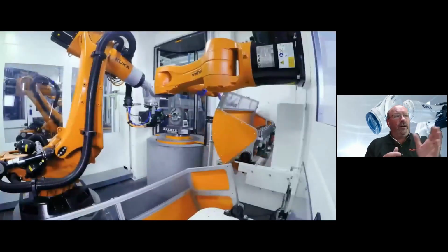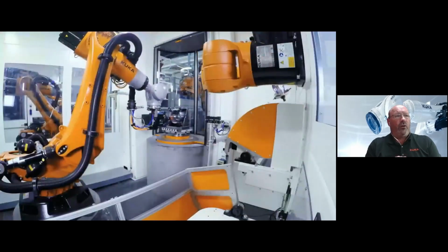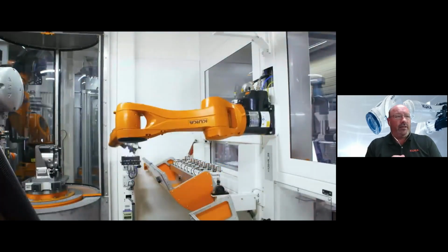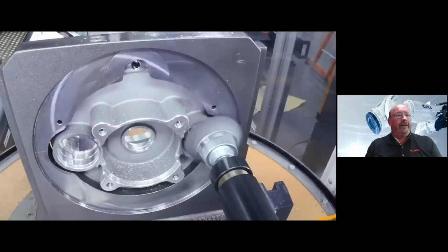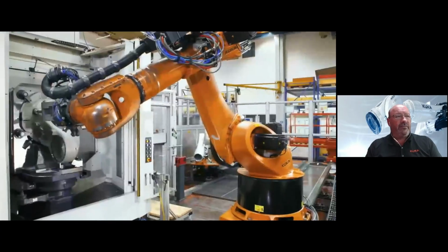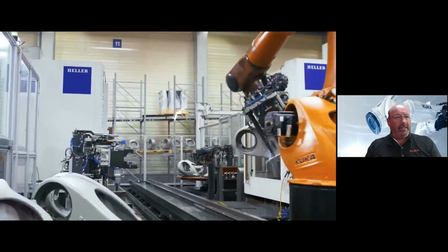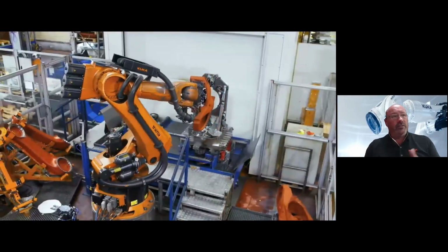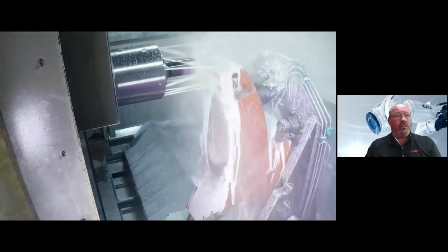And so we're showing here an example of having robots do more than just loading and unloading parts. You can see this particular operation has the robot doing, again, non-critical machining, doing some face milling, doing some material handling, as you see here, doing some tool changeovers. This is actually a sneak peek into KUKA's manufacturing facility. This is how we machine castings on some of our arms, some of our larger arms.